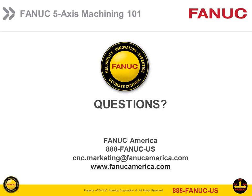Okay. Another one of our attendees would like to know, how often should I check the TCP parameters? Well, that's a good question. We would recommend, initially, to set it up, and then 3 months later check it again, to make sure your machine wears in, your ball screws wear in and everything like that. The machine settles, because even the level of the machine is going to affect it somewhat, based on where you have the machine.